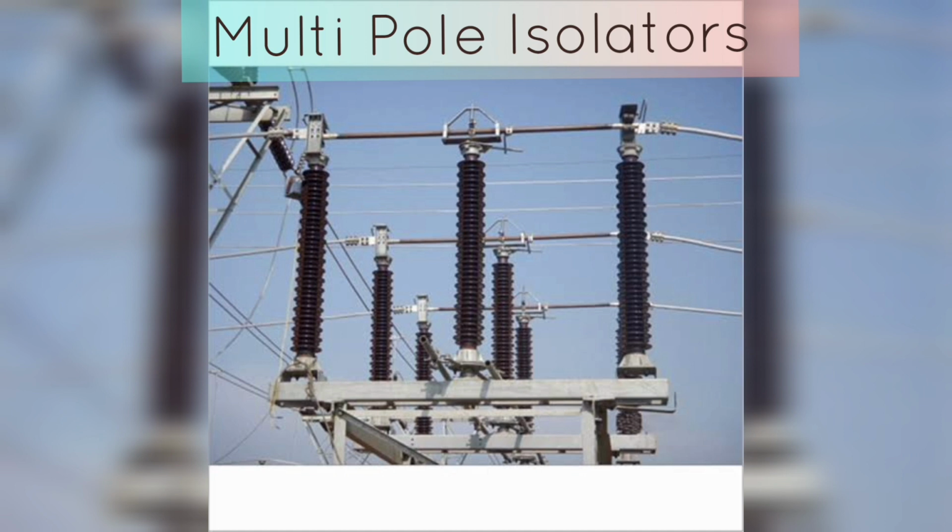One important feature of multi-pole isolators is that they are designed to be visible, so that the status of the isolator can be easily determined from a distance. They are typically fitted with visible switches or handles that can be easily identified as either on or off positions. It is important to note that while multi-pole isolators are effective at disconnecting circuits, they do not provide any protection against electrical faults or overloads. For this reason, they are often used in conjunction with other protective devices, such as circuit breakers or fuses.